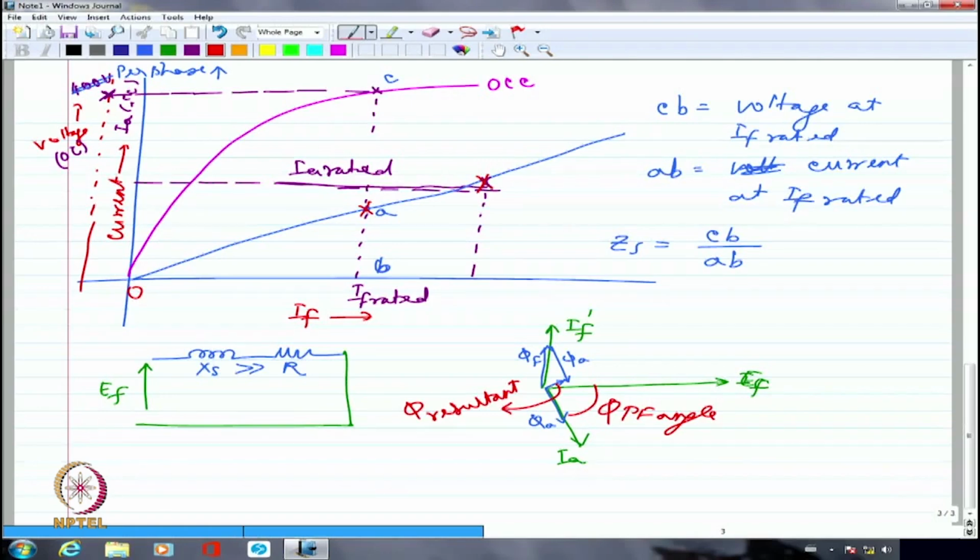So what has to happen is the generated voltage has to be increased. There is no other way. I repeat it. Infinite bus voltage is, let us say, 400 volts. Okay? If I am having huge amount of synchronous reactance in the machine and the current drawn by the loads in the grid are all lagging, the voltage might try to go from 400 to 300 or 360. It will plummet. It will go down. But infinite bus is going to say, you can't have lower voltage. It is not possible. If you can't have lower voltage, only way is to increase EF.